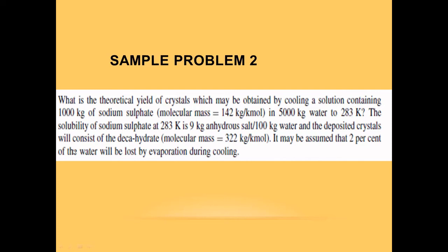Okay, the solubility of your sodium sulfate at 283 Kelvin is 9 kilogram anhydrous salt, so no water, per 100 kilogram of water. And the deposited crystals will consist of the decahydrate. Now, this refers already to your sodium sulfate decahydrate form, meaning the crystal that is separated from the mother liquor when your magma is processed is in the decahydrate form.